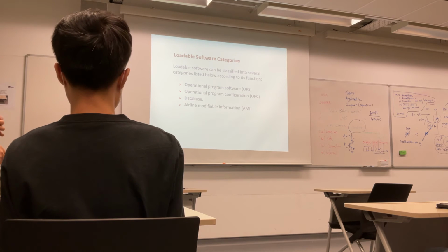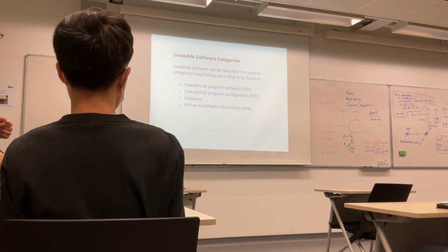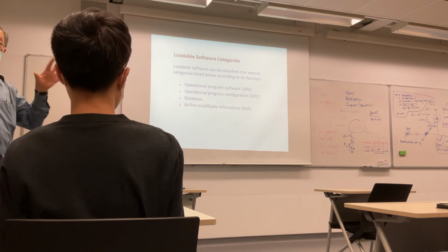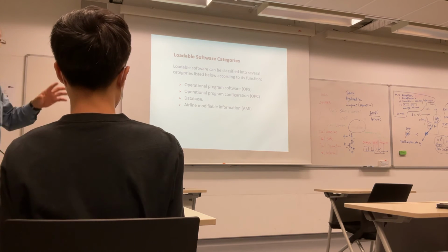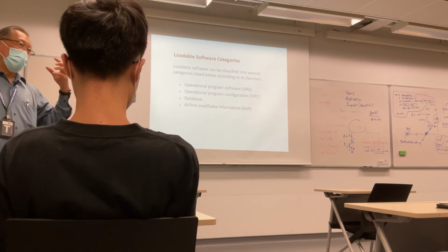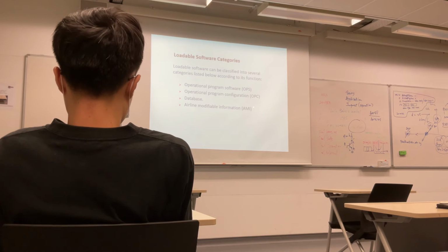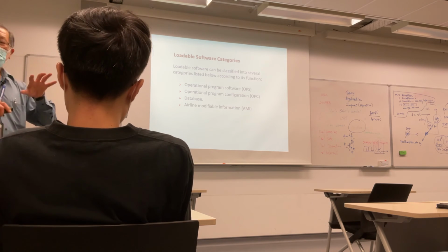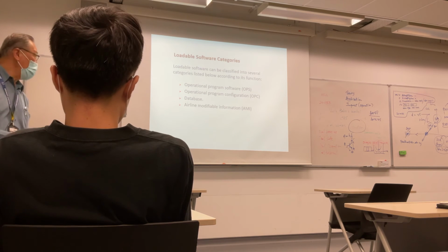So for loadable software, there are a few types. One is called operational software. One is operational program configuration, just a configuration. Then there is the database: your flight management computer has the nav database that needs to be updated every 28 days. So every 28 days you have to put the disk in there and change it. Now there's this thing called AMI. This is the airline's own system, independent of the manufacturer.